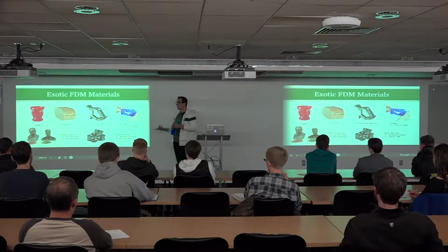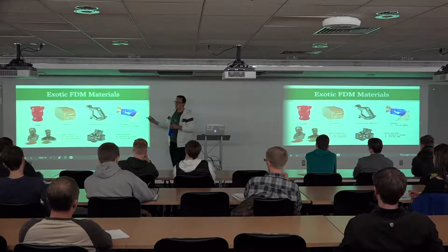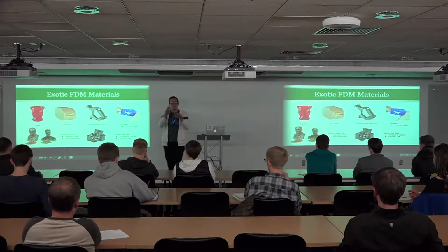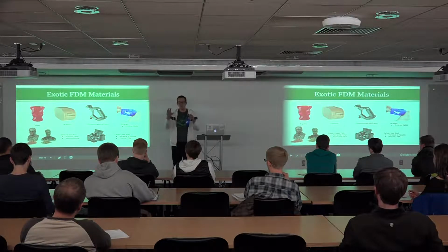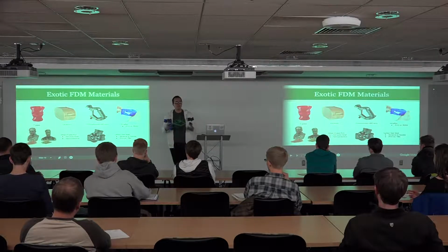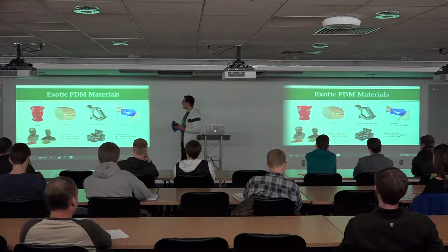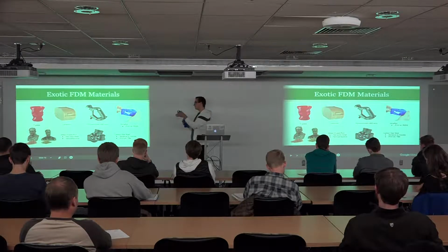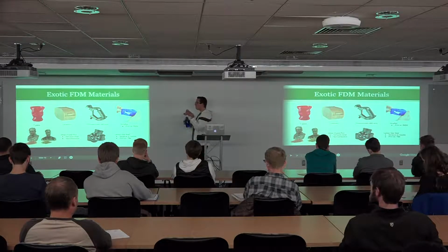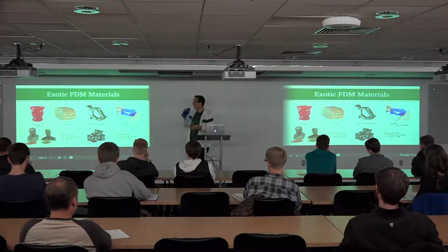The iron one is magnetic. Unfortunately, the copper one is not conductive because the copper bits are floating in a polymer matrix. So they're basically floating in a dielectric. So there's no way to get current through them. Although supposedly you can get maybe a little bit, but super high resistance.